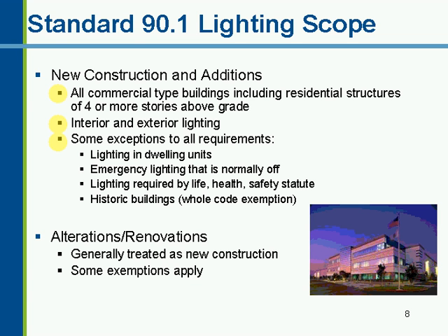One common confusion here is if a company has a corporate policy on design, for example, that says this is how we want our spaces designed. That does not fall under this exemption. These are only for actual statutes themselves. Historic buildings have a whole building exemption for all the requirements in the code. So if your building is on or capable of being on a national, state, or other historic register, the lighting within that can be exempted as well.